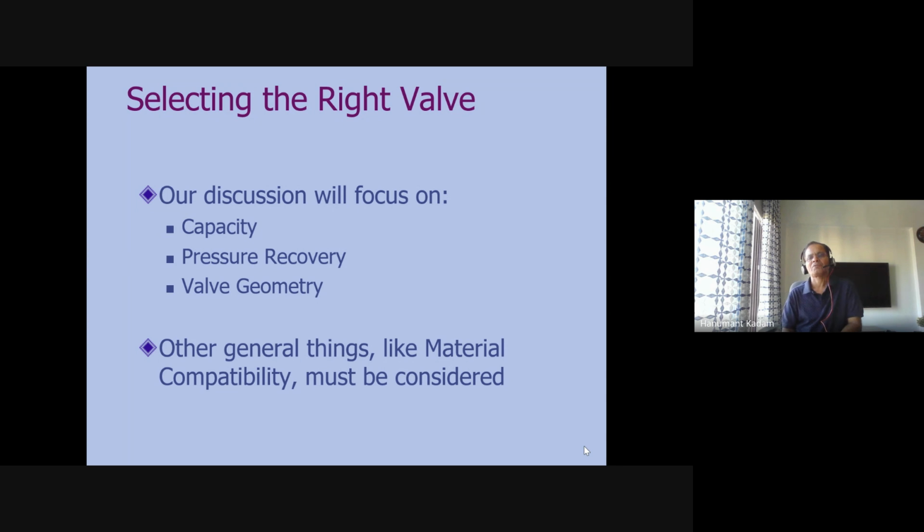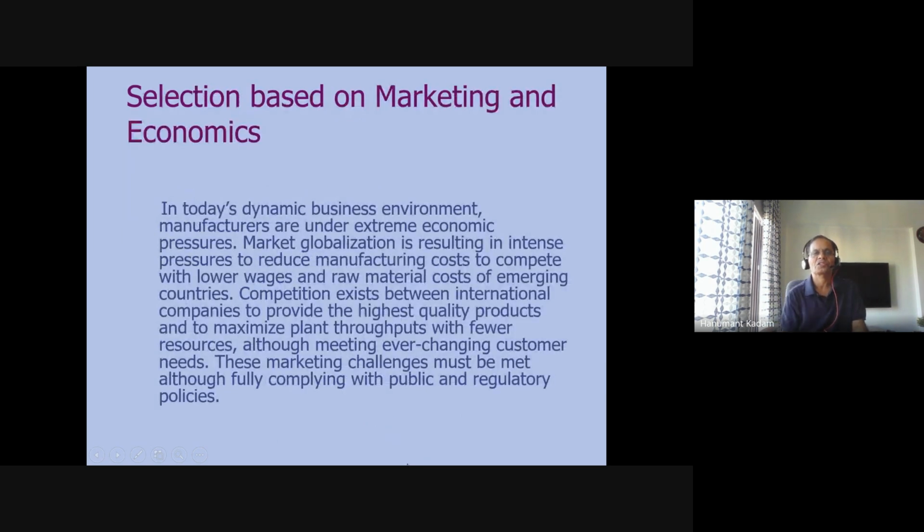It means construction material, because of your flowing material, type of material like acids, slurries, or gas, temperature, corrosiveness, and properties of that particular liquid. All these are related, and accordingly you have to select the construction material, like the type of steel for construction.